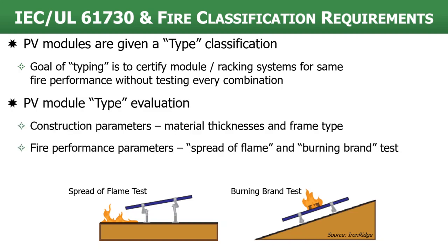The PV module type evaluation really depends on how the module is constructed. There are material thicknesses, like the thickness of the glass on the front, the type of frame, and also the back sheet. Very common is Tedlar, but there are some modules that have a glass back sheet. So those are glass on glass modules. But again, the module type evaluation depends on the construction parameters of the particular module.